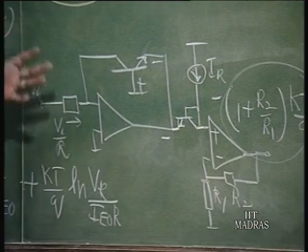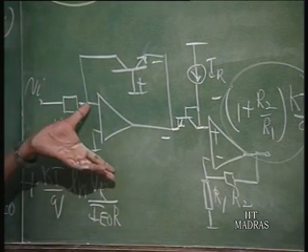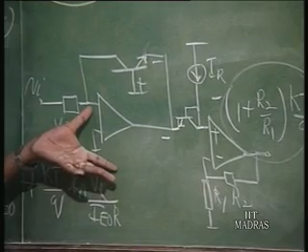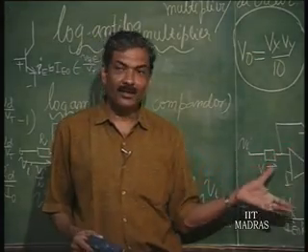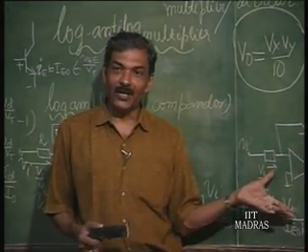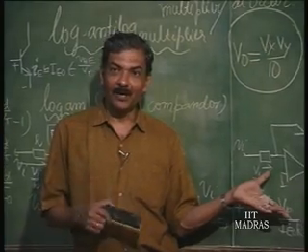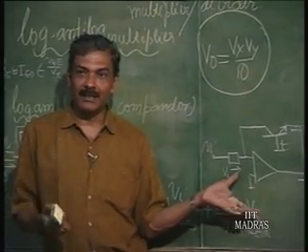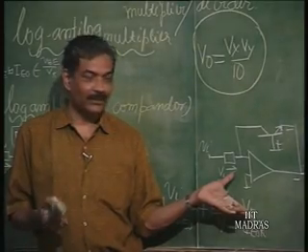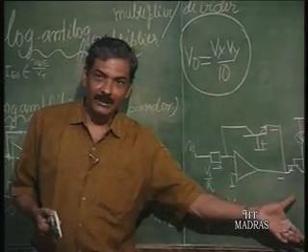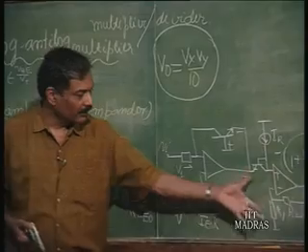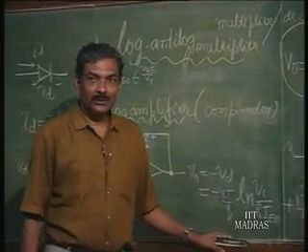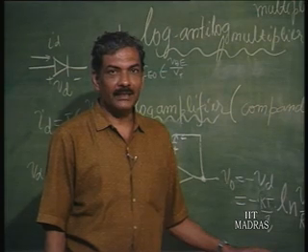First, therefore, we will understand how to design a good log amplifier, then how to design a good anti-log amplifier, then see whether such compensation is necessary at all for multiplier, because log operation and anti-log operation, when you are doing, automatically they may get compensated. So, there is no need for providing separate compensation in a multiplier. Okay. So, we will now discuss a good anti-log amplifier design.